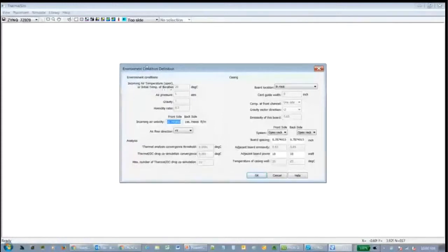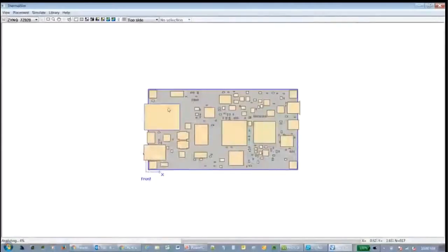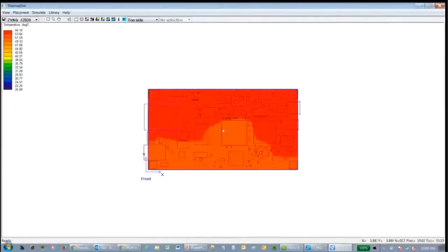The simulation engine's extremely fast in checking your design for you, and then it'll give you a heat map. This wasn't a very good example, unfortunately. A heat map of where the board is hot and cool, and then you can play around with putting stitching vias in. I can add heat sinks, heat pipes, thermal vias in there, re-simulate again, and see if it assists with my cooling.